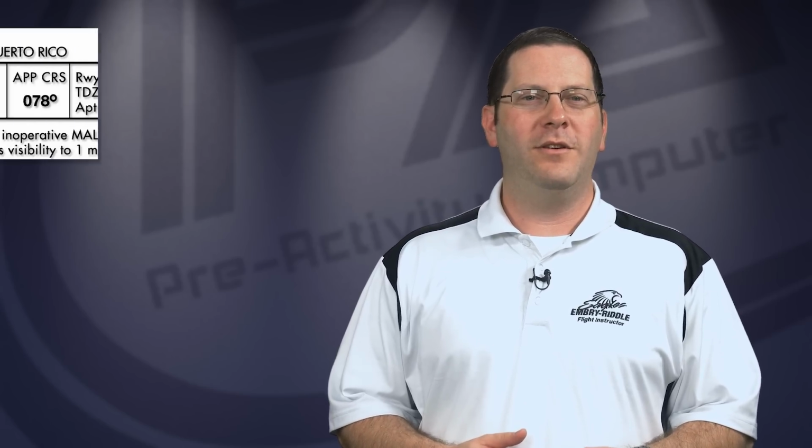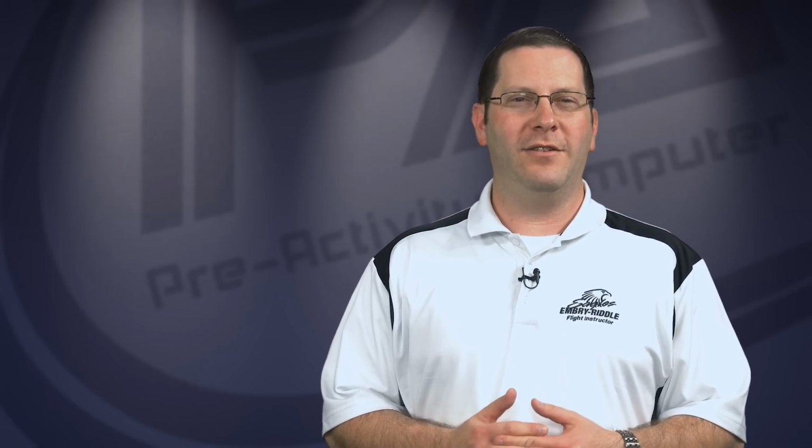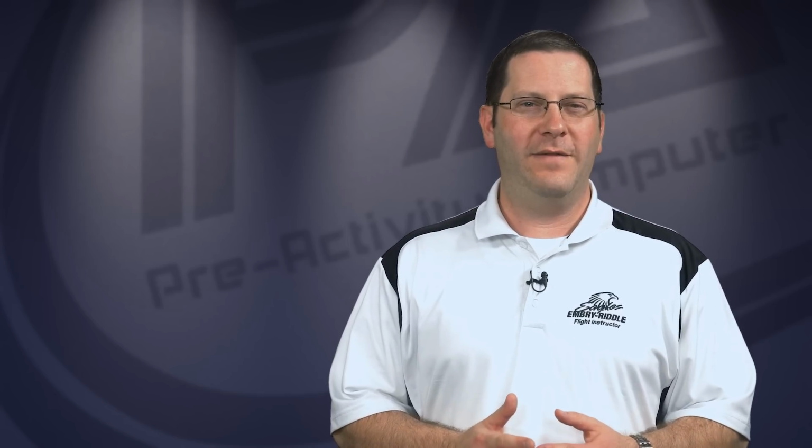Flying an ILS starts with tuning and identifying the localizer frequency. For this example, we'll tune and identify 110.3, the ILS 8 into San Juan International Airport in Puerto Rico. The approach begins with first aligning yourself with the runway using the localizer. This is usually done through ATC vectors or with a procedure turn.